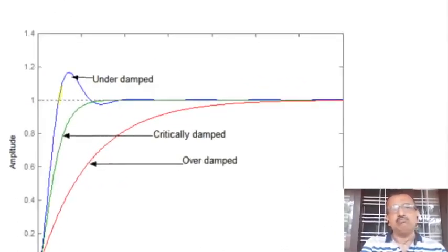All of you being electrical engineers or mechanical engineers, you know the shape of a sine curve. And what is happening to this sine curve? As time goes to infinity, that sine is decaying. So that is why our step response has this shape. For an underdamped system, the step response has a sinusoidal component which is dying out. So we can think of many practical examples where this kind of phenomenon could be seen. Like you give a step input, there will be some oscillation and it will die down.